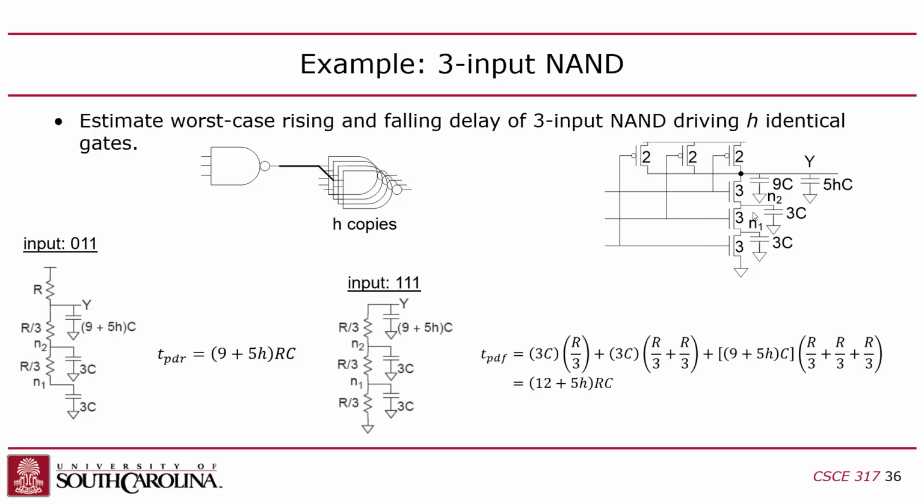So in other words, when I used to do this back in grad school, 3 inputs was basically the max. You'd never see a gate with more than 3 inputs, unless there are special gates like an AND-OR-invert gate, which is a kind of complex gate. I think those might have 4 inputs. But generally speaking, 3 or 4 inputs is the most you're going to find, because of this crazy capacitance you get when you have all these transistors in series.